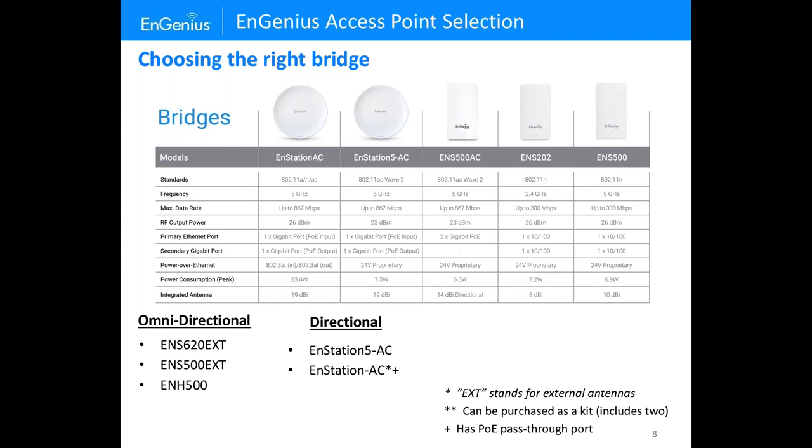And if you're off to the side, you could be a couple 100 feet off to the side or not even within the beam heading and still do a point to multi-point link. I think that's a misnomer a lot of people overlook, the fact that you can be really close to these. I did one where I was directly behind one, about 100 feet, which is really close, but then the other one was pointed a quarter mile down the way.